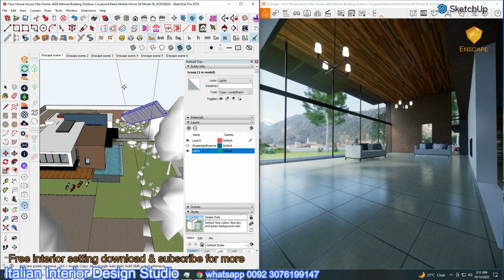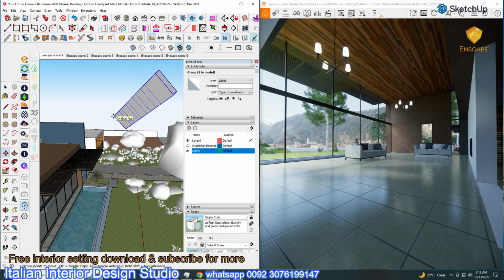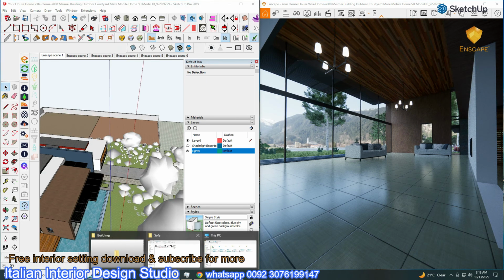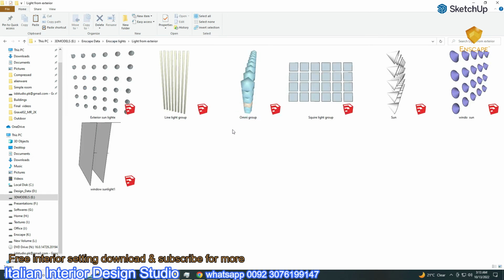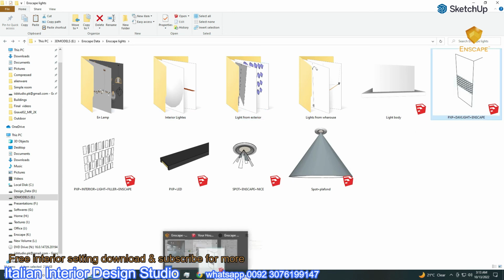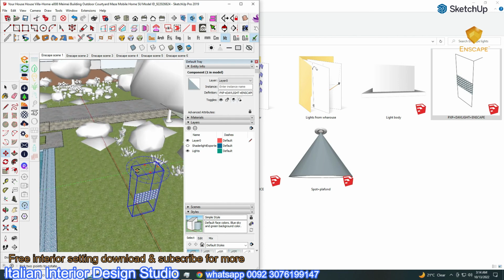So keep your floor lighter and walls also lighter. In some walls you can apply dark color. The scene depends on the windows. If you have a big front window, you need fewer light objects for the interior. But if you have a very closed room scene, that will be a difficult task. In my other videos, I have made scenes with very small windows.